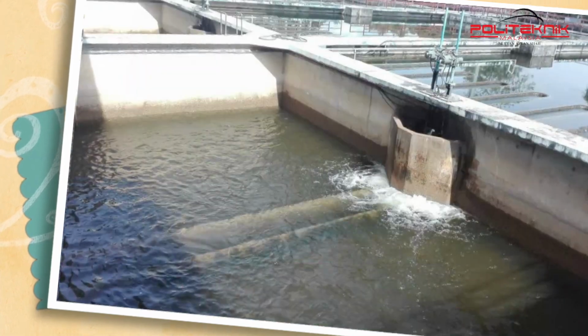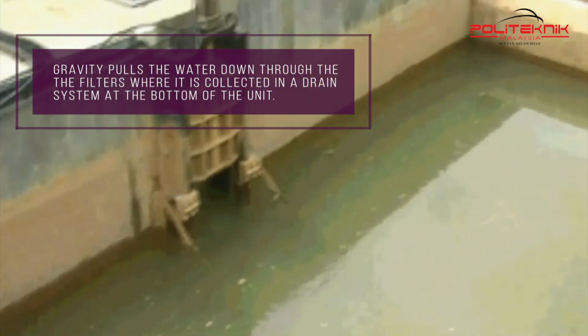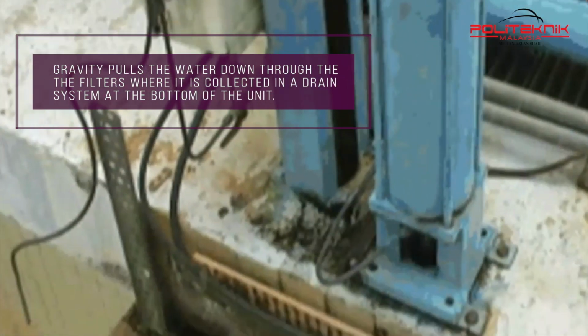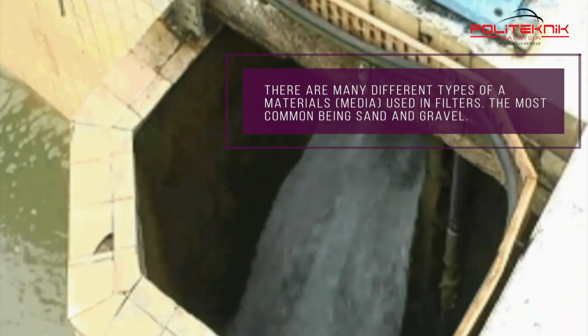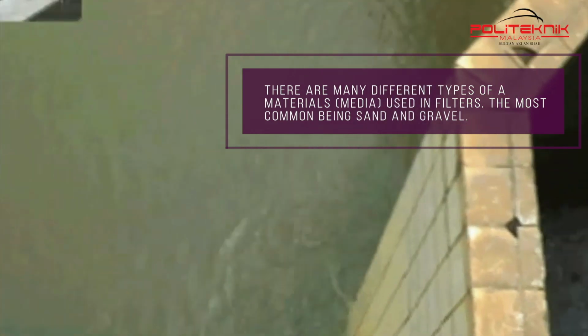Clarified water enters the filters from the top. Gravity pulls the water down through the filters, where it is collected in a drain system at the bottom of the unit. There are many different types of materials or media used in filters, the most common being sand and gravel.